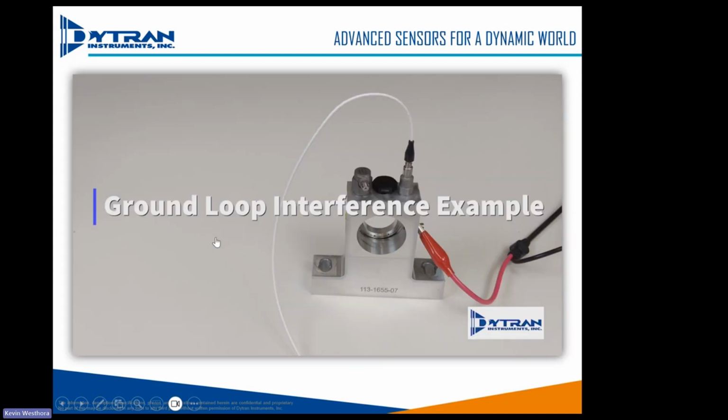And then the next thing I want to talk about is electrical isolation. Okay. Most accelerometers that we offer, that anybody offers, are not electrically isolated. So it's important to understand if your test requires isolated sensors, check to see if your sensor is isolated or not. If it's not, make sure you isolate somehow, whether it's through a base, whether it's through the adhesive, or whether it's through Kapton tape, whatever you want to use to isolate.